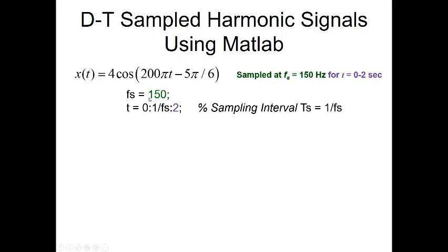And so by defining the sampling rate and then taking 1 over it, using it as the interval of this, we get the sample time values starting at t equals 0, then 1 over fs, 2 over fs, 3 over fs, and so on, resulting in 1 times t sub s, 2 times t sub s, and so on.